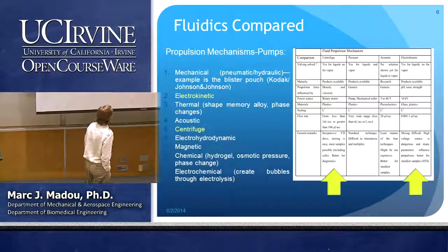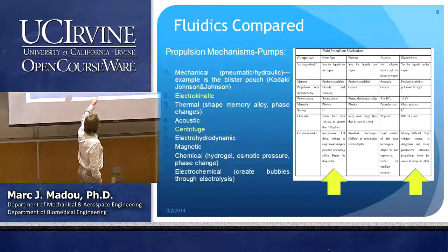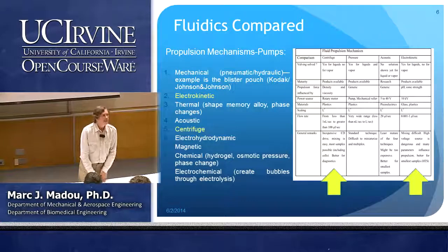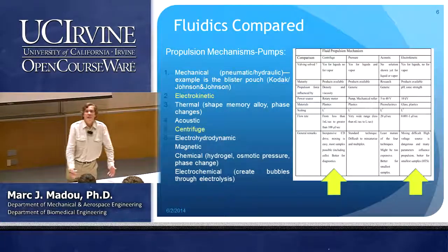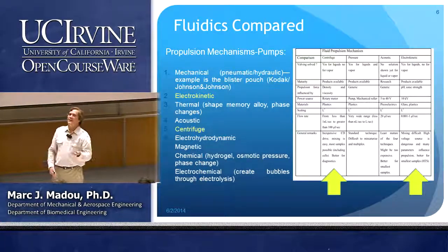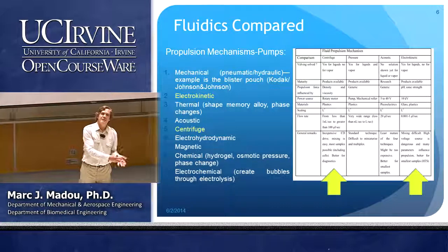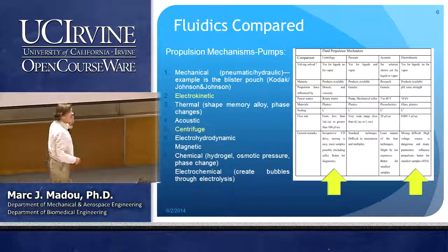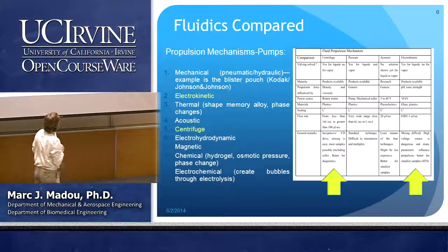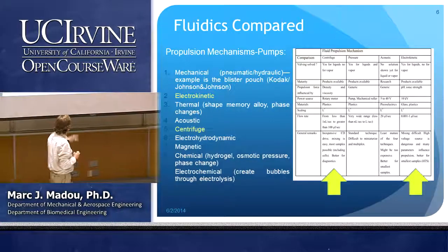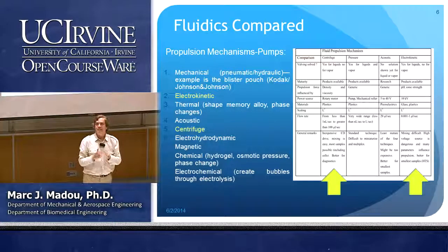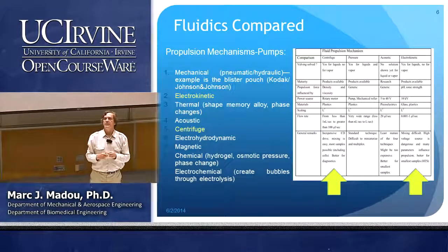A power source, so the propulsion force is influenced by, that's important. You know, that liquid that you're using could be very different from sample to sample. Could be milk, could be blood. And you don't really want the pumping force to be dependent on the nature of the liquid. And so with that in mind, if you go across in the row, propulsion force influenced by, in the case of centrifuge, it's the density and viscosity that dictates the propulsion. You'll see the equation in a little while.